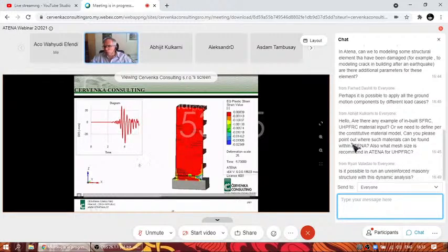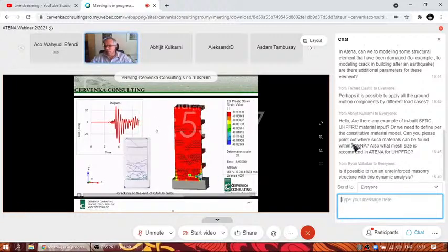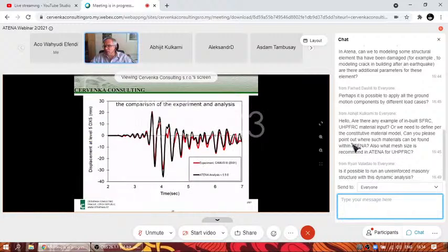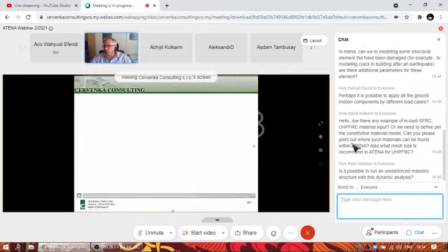Also, in this 18-story building, the slab was elastic, because we were not so interested in that. But there is no problem really to activate also nonlinear elements. Of course, this makes the analysis more demanding. Problems then will be that the slabs may start failing, so you may have problems reaching convergence and so on.